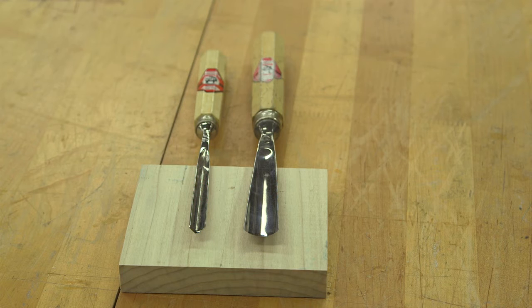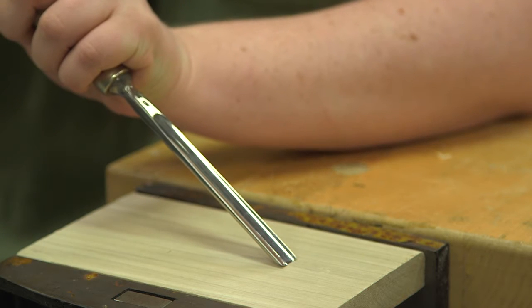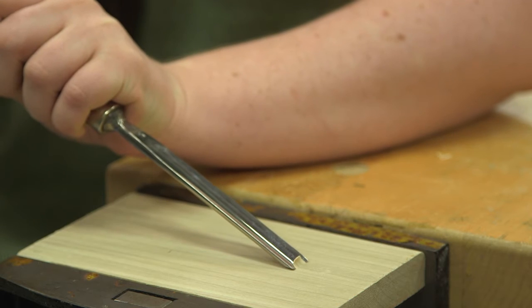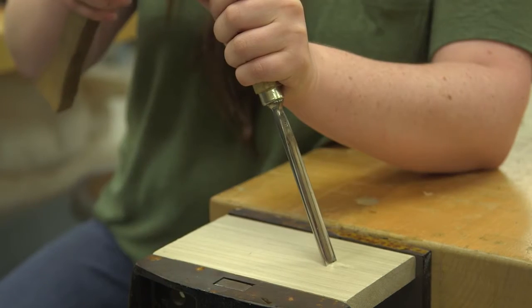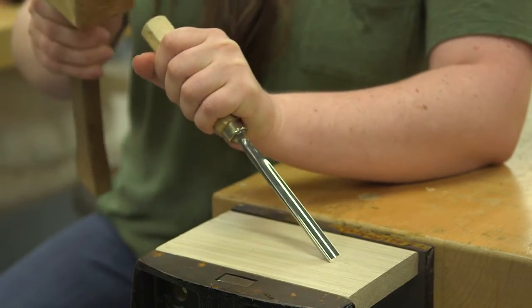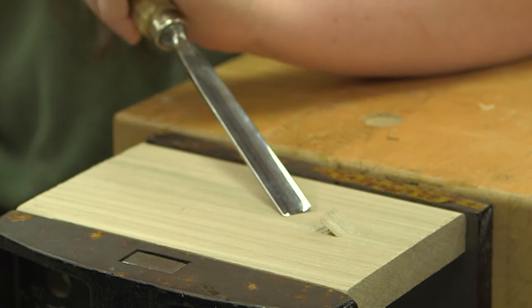Taking a closer look at carving tools, each chisel is made up of the same parts: a cutting edge, the top edge tips or wings, and the shaft. It is important when using a chisel or gouge that you are only using the cutting edge to remove material. The wings should not go below the surface of the material. Wings below the surface of the wood will cause the tool to create tear out and a rough cut.